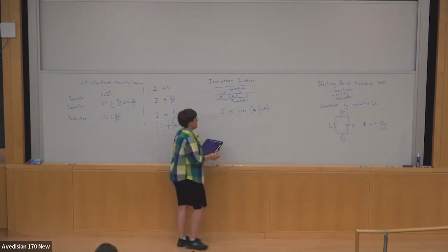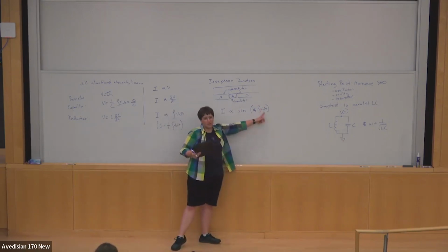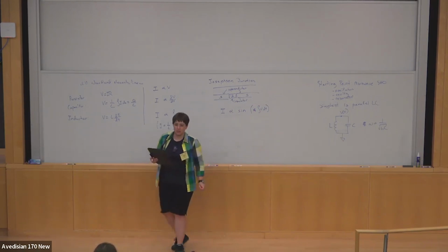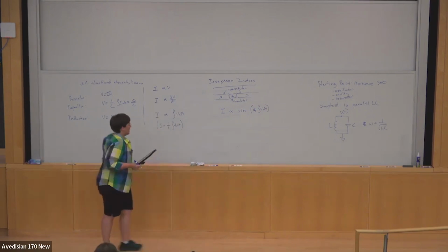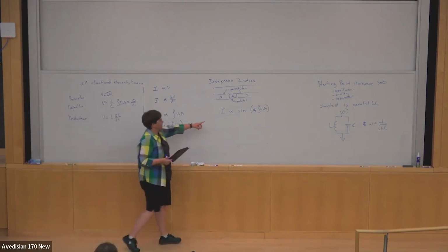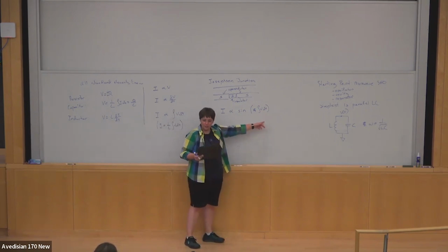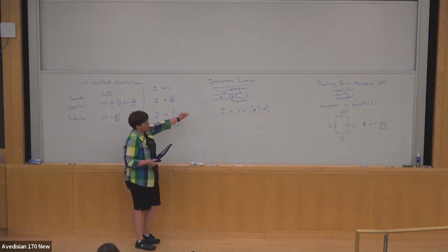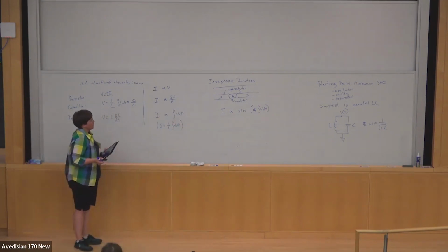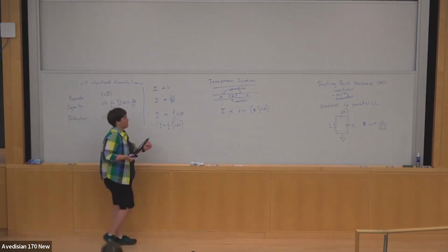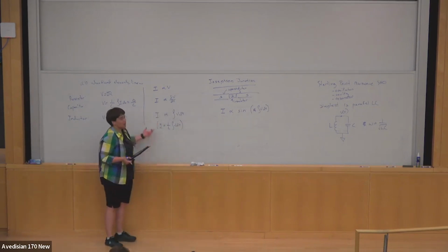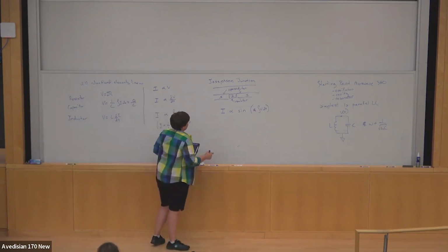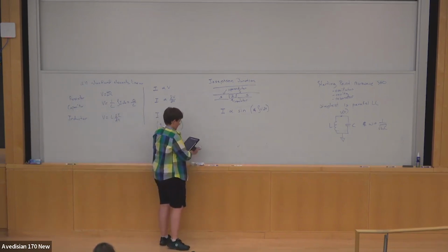is that the current in a Josephson junction goes as sine of the integral of the voltage. This squiggle stands for various numerical and unitful constants, which I don't wish to bother with at this time. So this is clearly nonlinear because it's sine of the voltage. And so this is going to be our ingredient. And now, can we get some intuition by comparing this thing to one of the linear elements that we already know about? Right. And so that's what we're going to look at next.